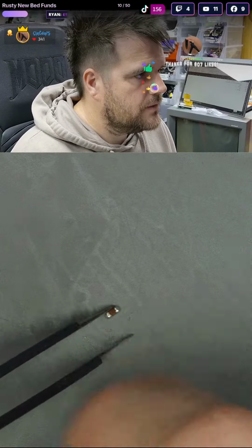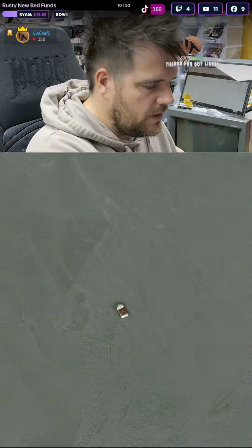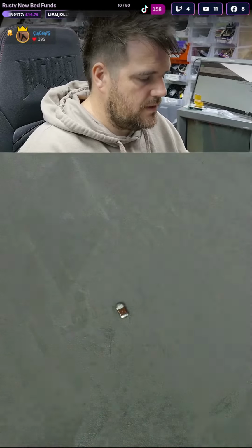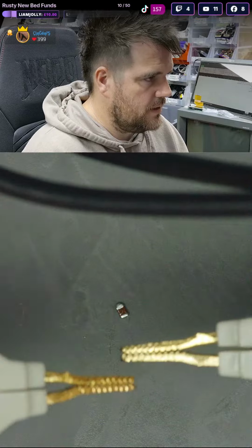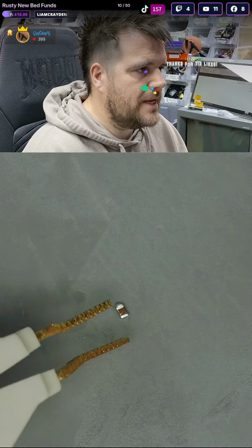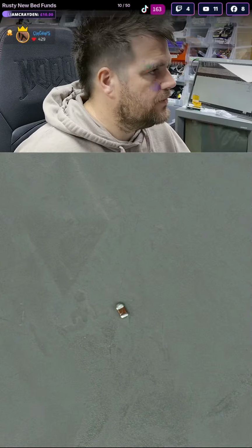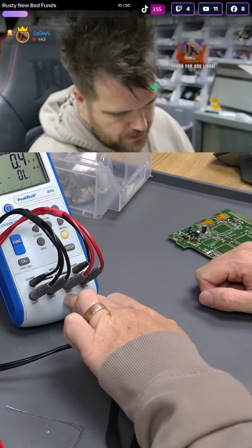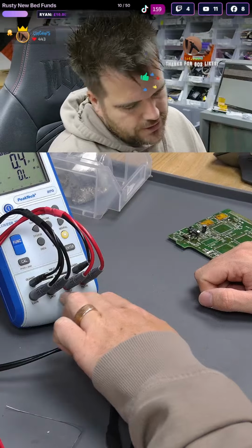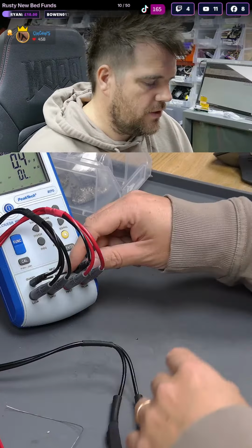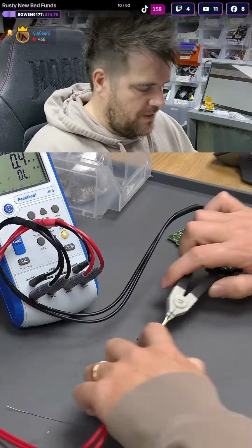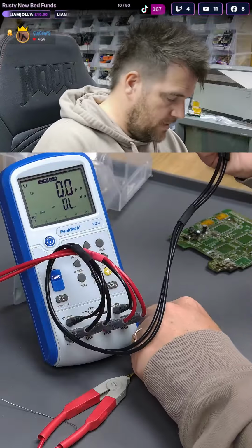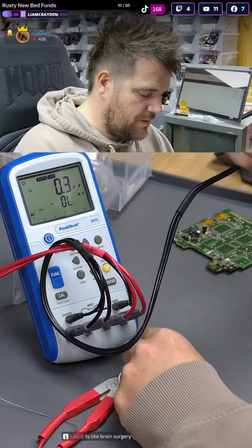Get that back into view, and now the goal with the LCR meter is, you've got these big prongs. These have 2 pins each. I can remake it so I can just grip on and it's accurate enough, but technically, because these are proper, they have 2 pins. One is for the high potential and high current, so you've got a potential and a current pin going in, and a guard. So it's basically keeping it accurate, but you can do it without that being super accurate, and I could rewire these so I can just use a single gripper to grab on.